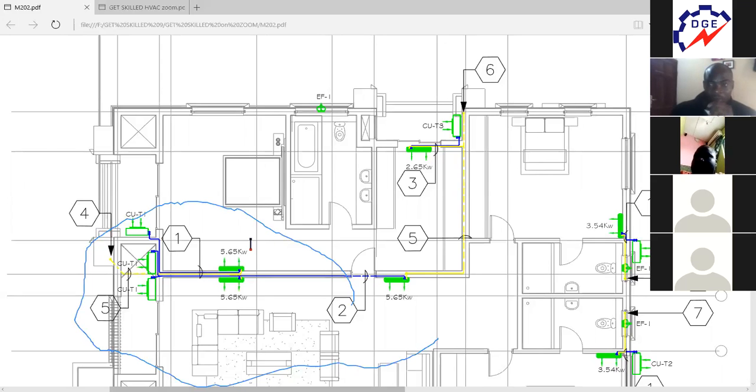So from that 29 square meters, we multiply by 0.189 kilowatts, and you will come to something around 5.4. I think it was like 5.4 or 5.5 kilowatts of cooling that will be required for this space. Then one other thing that is extremely important for air conditioning is location.